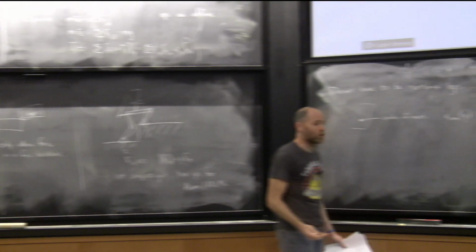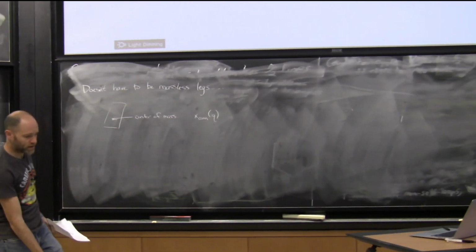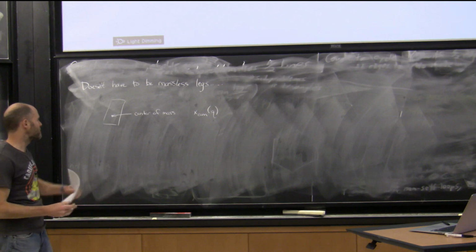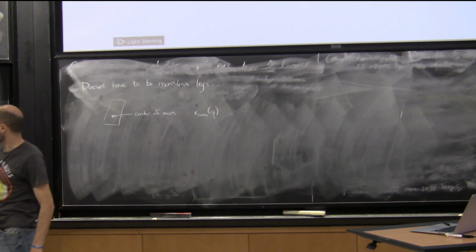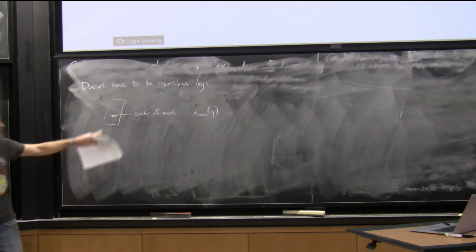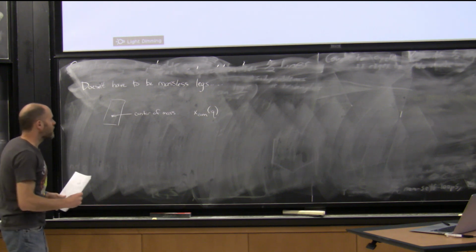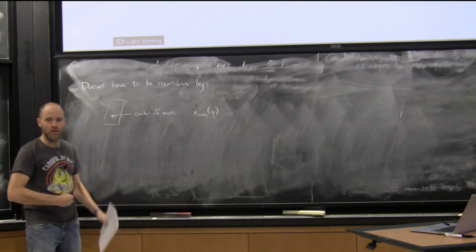But no matter how complicated your robot is, even no matter how it carries its mass, it could have really heavy feet and really light torso. It'd be a sad robot, but I could still say that my goal is just to produce forces at certain points to move the location of my center of mass around. And the center of mass is just a position, it's a point.